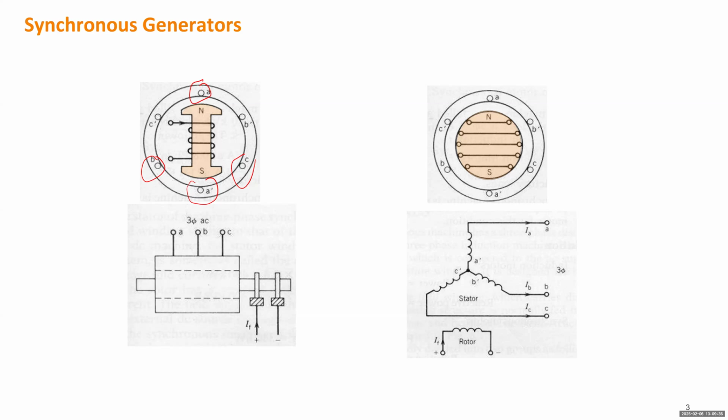But the rotor will be revolving inside of the stator, and it has a very small air gap, for instance at this position between the N and A, but in the perpendicular direction it will have a much larger air gap. Definitely, this figure is just a very simplified layout of the generator. But if you see real pictures of the inside of the rotor, you can still tell in which direction the air gap is bigger and in which direction it is smaller. So you can feel the change of the air gap due to the revolution of the rotor.